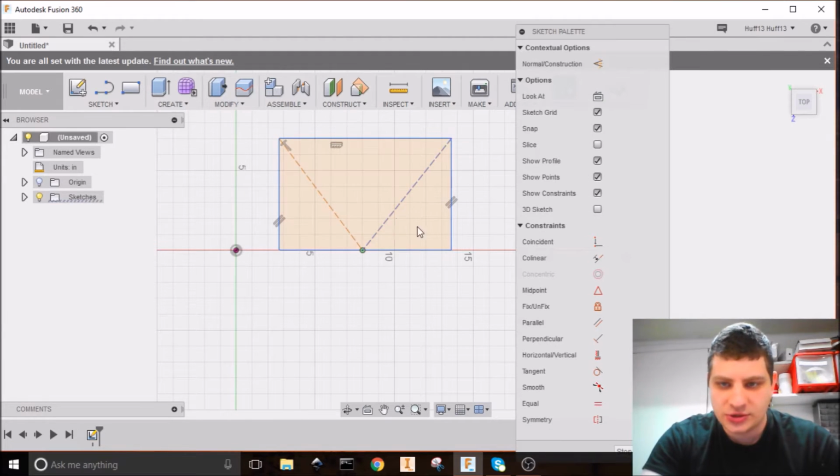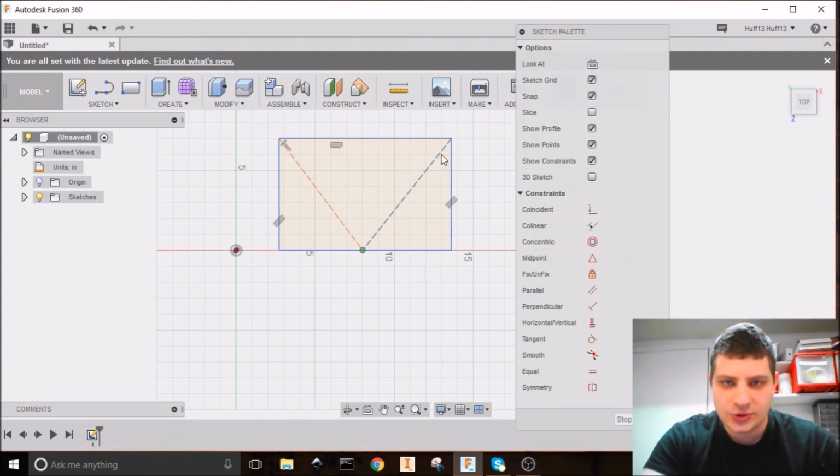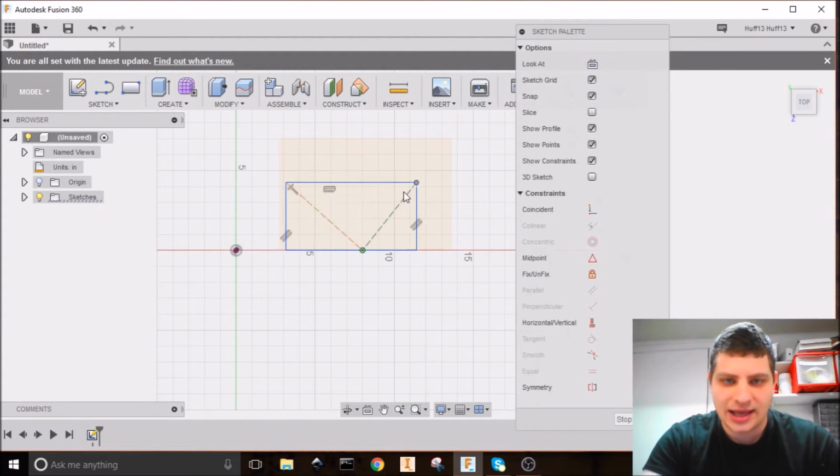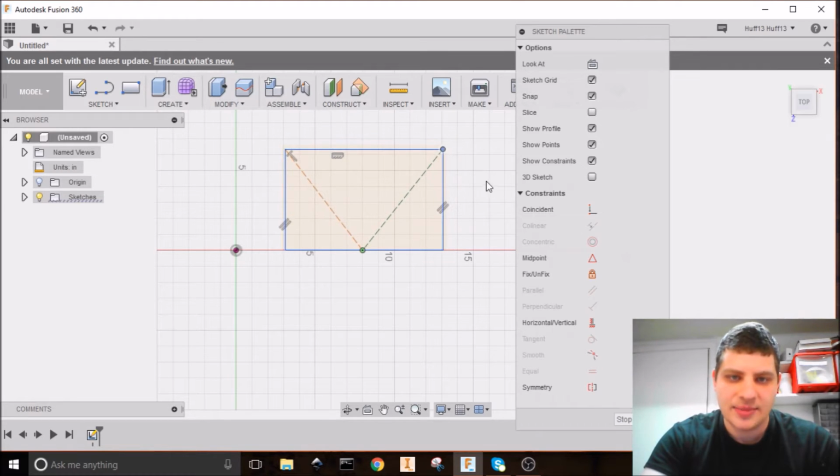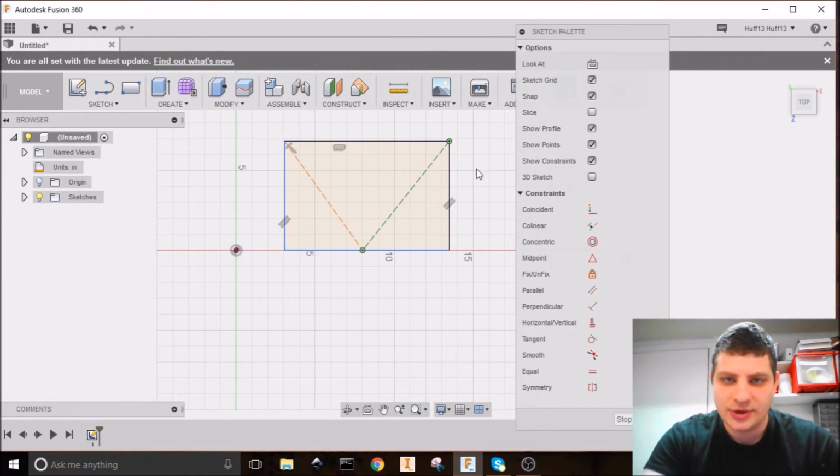And if we wanted to do that to a line too, we could do it to a line, and now that line will never move. Now it will get longer and shorter, but it's going to stay at the same angle with that fixed endpoint. If we wanted to lock that line down completely, we could fix that, and now that's not going to move at all, except that way. There we go, because that doesn't affect the line.